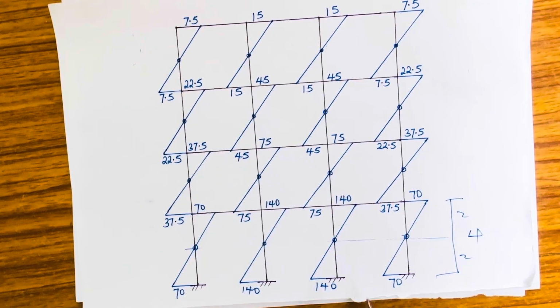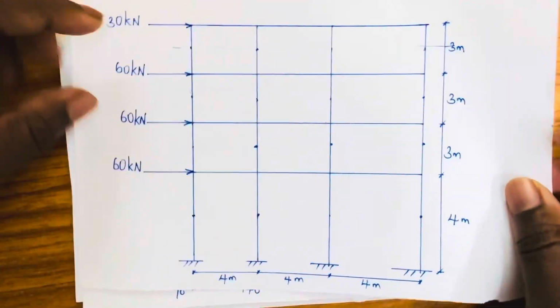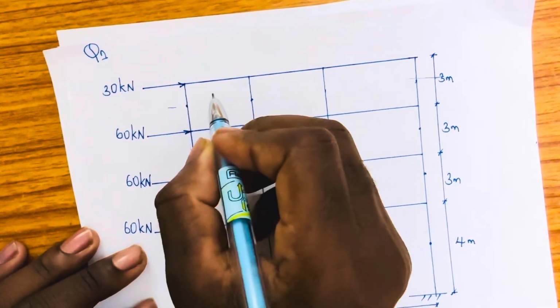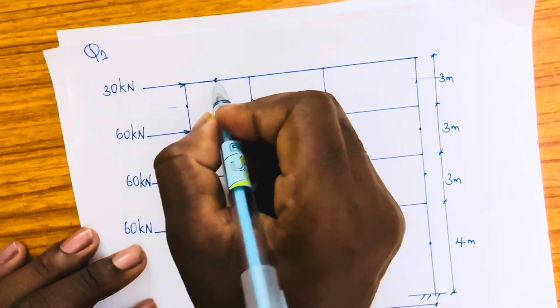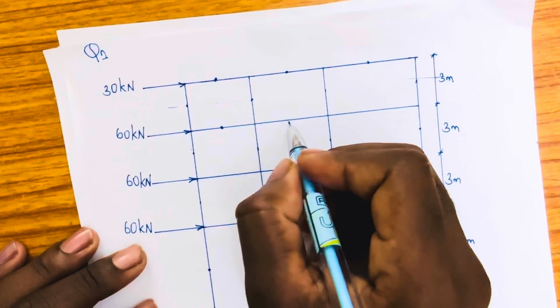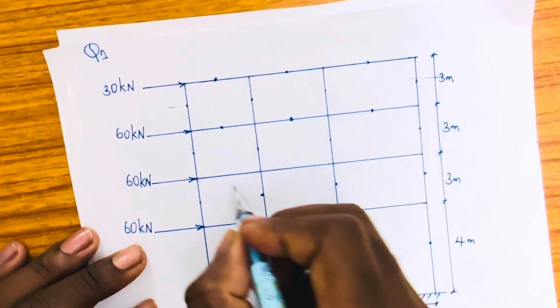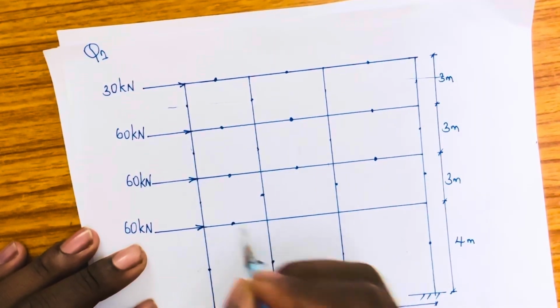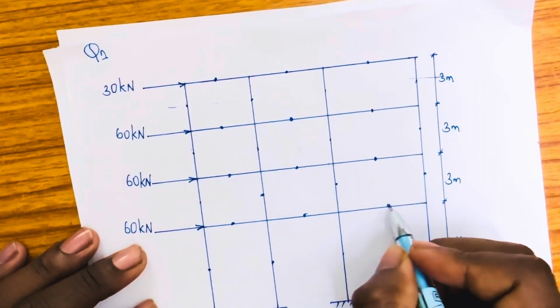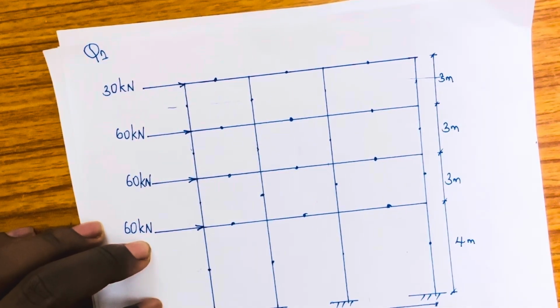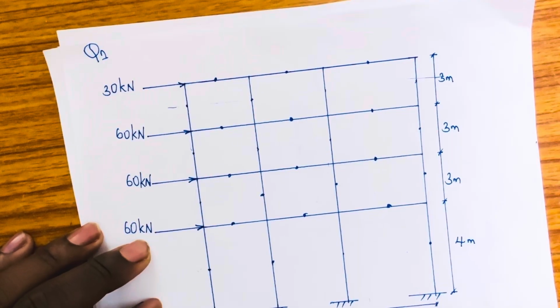Yes, so if we're done with the column, let's look at the beam shear. So how do you get the beam shear in this case? The same thing, you have to first start by marking all the points of contraflexure of the beam. So the mid section or the mid span of all the beams. Okay? So remember the horizontal ones are the beams, the vertical ones are the columns. So we're done with the columns, we are now doing the beams. So you mark all the points of contraflexure. And we're done.